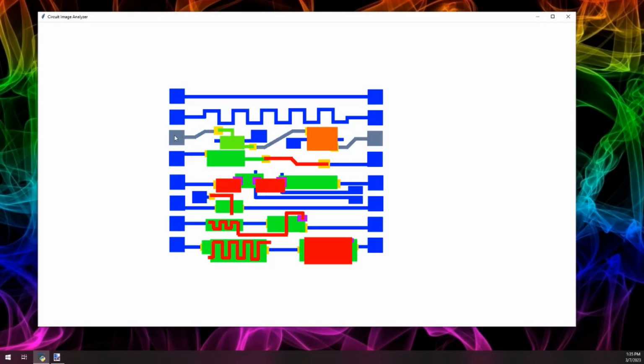And so you can see here I've got one circuit selected. It's going from this piece of metal through the via into the diffusion layer, through another via to metal, to another via to polysilicon, then a final via into the last bit of metal here. And then these two pieces of metal underneath these extra bodies here, because there's no vias connected, they're not selected.